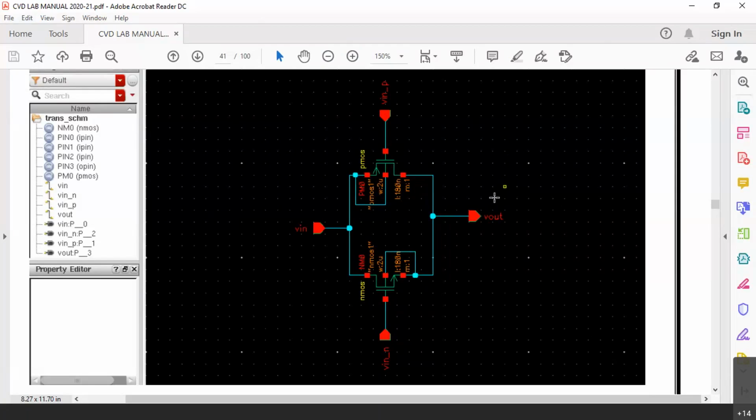So now, before proceeding to the layout of this circuit, I want to conduct a small viva. As Deepak has explained in detail, PMOS passes a good 1 and NMOS passes a good 0. For the same purpose, we write PMOS at the top and NMOS at the bottom in regular static CMOS gates. We have been working with static CMOS, inverter, NAND gate and NOR gate till now, and you already know that PMOS is always at the top and NMOS at the bottom. The reason is that PMOS passes good 1 and NMOS passes good 0.